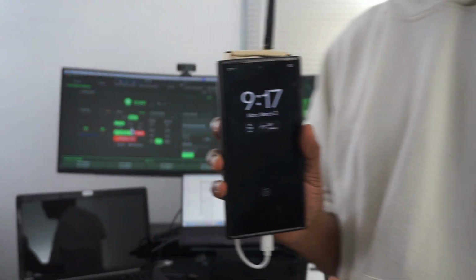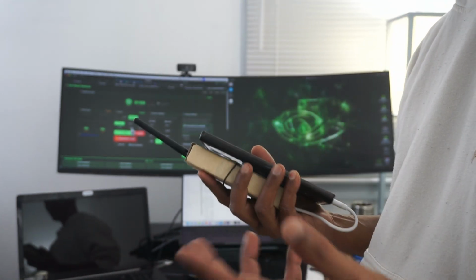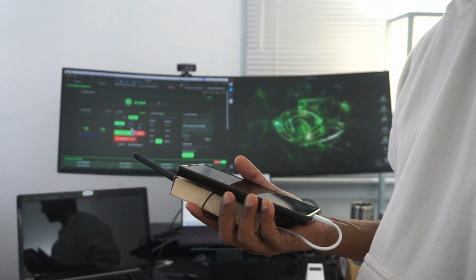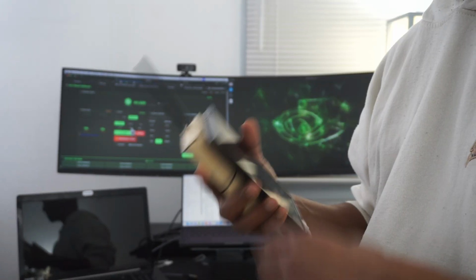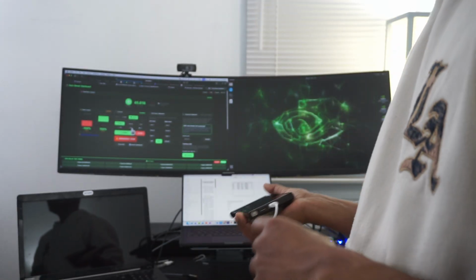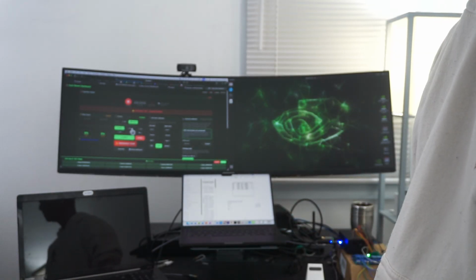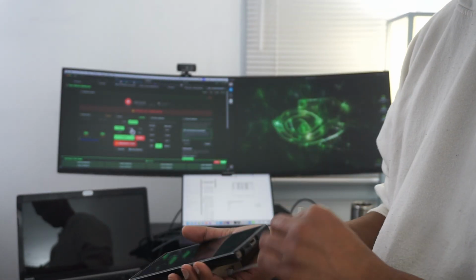So the flow here is the Android app on this phone connected with this RF works as what they call a dead man switch. If for some reason I think that the mower is losing control, it has lost connection, or it is going into a neighbor's yard or hitting someone, if I just disconnect this, that thing stops. So it's a heartbeat. Within a second, if it doesn't receive this, that stops.